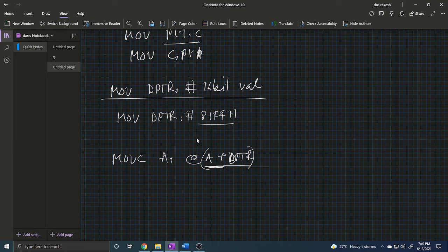So this is the working mode of this instruction. Basically this instruction moves a byte of data located in program code ROM into register A, and this ROM location is selected by DPTR plus the current accumulator value. It is basically used when we use an array of code or an array of data. Therefore if the accumulator content equals 00, then DPTR starts from the base address, with an incremental value depending on the array size.